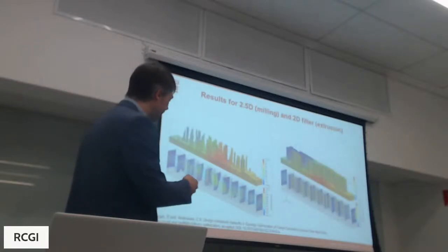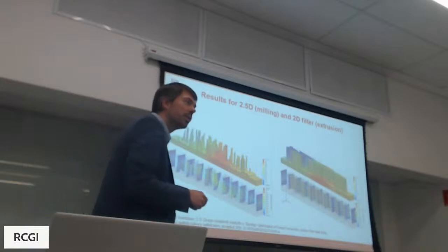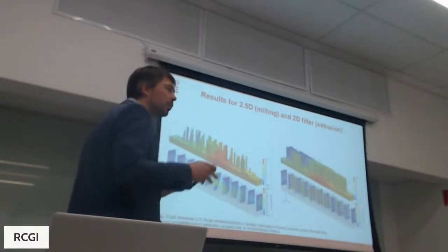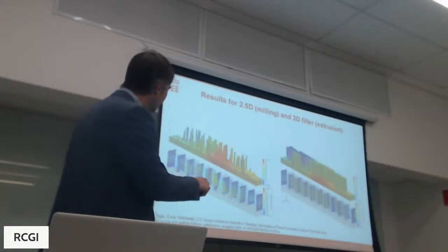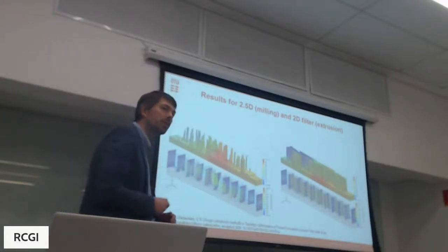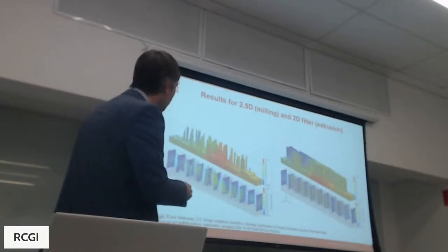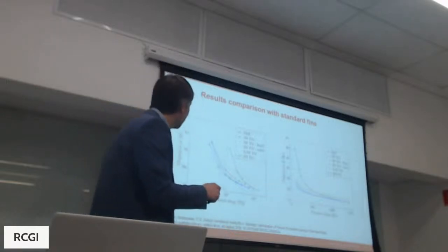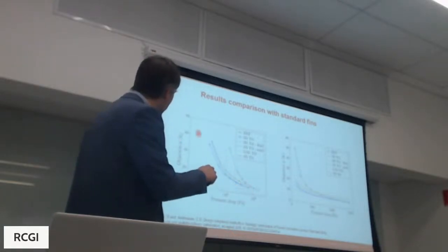There are different ways. We definitely see that with, for instance, the extruded designs, if we look at the flow here, not much secondary flow is happening, right? And that's of course because you cannot really induce secondary motion. But with 2.5D design, you are actually able to create a landscape that can induce some secondary motion. So this one actually tends to perform pretty well. We can have a comparison study here of the reference that was just the fins. So it looks like here, and we see that it performs relatively well. The objective here is the mean temperature of the heat sink, at different pressure drops.